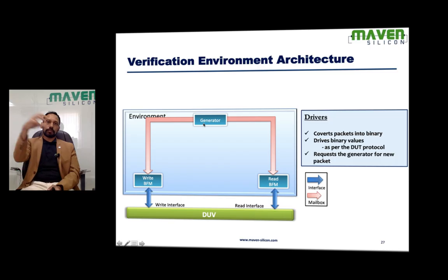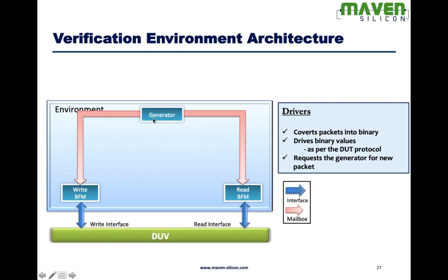It collects the packet from the generator, it converts the packet into binary, it drives all the binary values as per DUT protocol. So obviously the driver is going to be time consuming because it has to follow the DUT protocol. Definitely there will be time consumption in terms of clock cycles. Once it's done with the packet, it informs back to the generator to send the next packet.